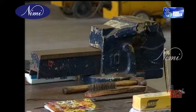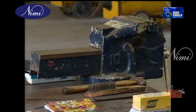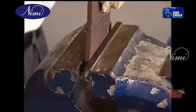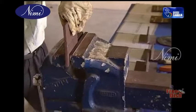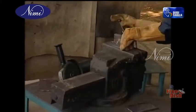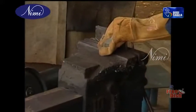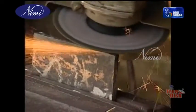This is a bench vise, which is commonly used in workshops. Vises are used for holding work pieces. They are available in different types. A bench vise is made of cast iron or cast steel. It is used to hold work while preparing the edges of sheets, plates and pipes by chiseling, hacksawing and filing.